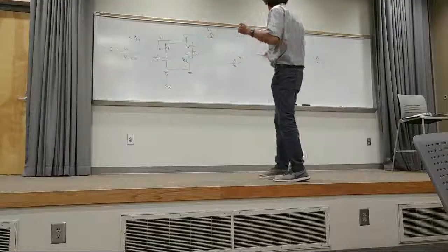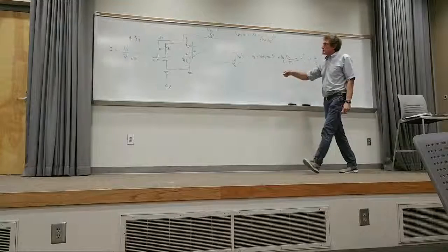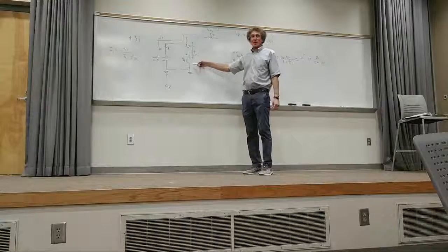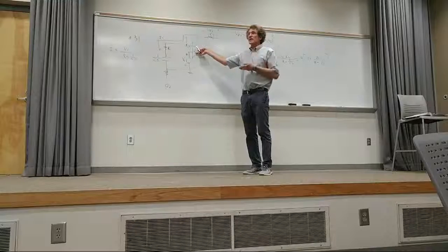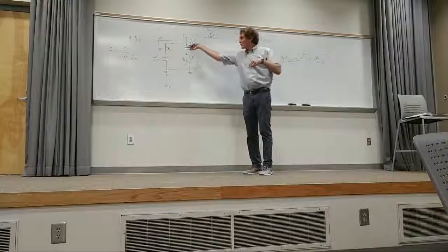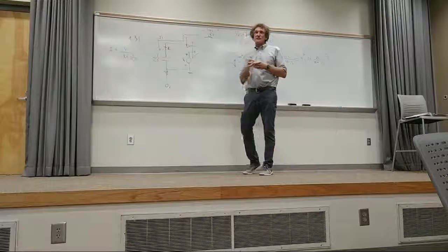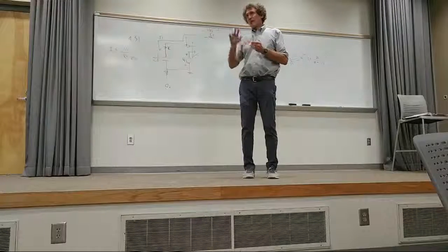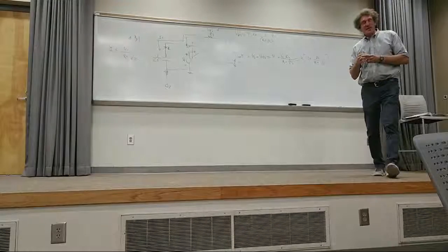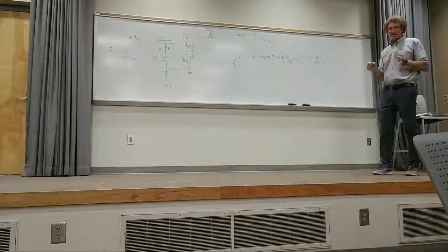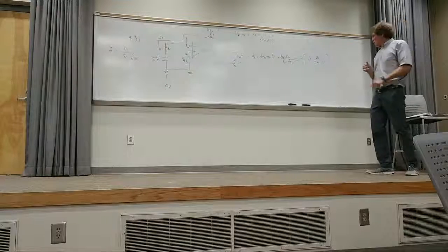You'll notice one thing about this, it's not inverting, is it? Now, that's why they call this the inverting terminal and this the non-inverting. Whenever you put a voltage, no matter what the network is, where you're feeding the negative terminal primarily, like either through a resistor or whatever, then you'll get an output that's inverted. When it comes to the positive terminal, it won't be. That's generally true, there are some things that will make it not true if you really work at it, but that's basically it. Are you with me, class? Y'all see it? Gotta do another one.